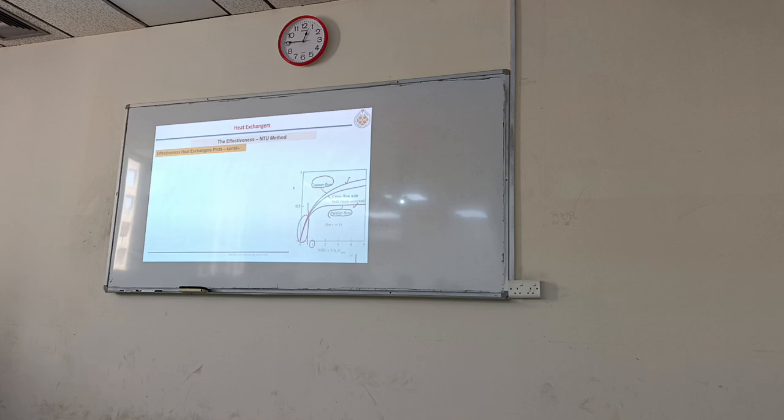This is another observation. Here this graph is shown assuming C is equal to 1 for all heat exchangers. The same is applicable for other values of C. Always counterflow will be highest, parallel flow will be lowest, and all others will be in between these two.